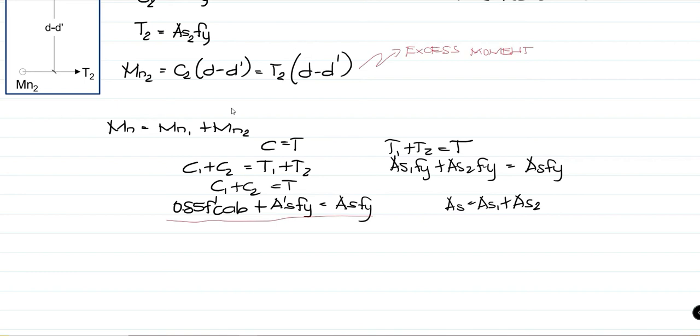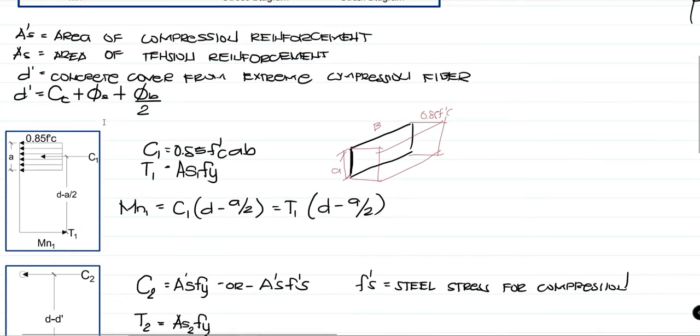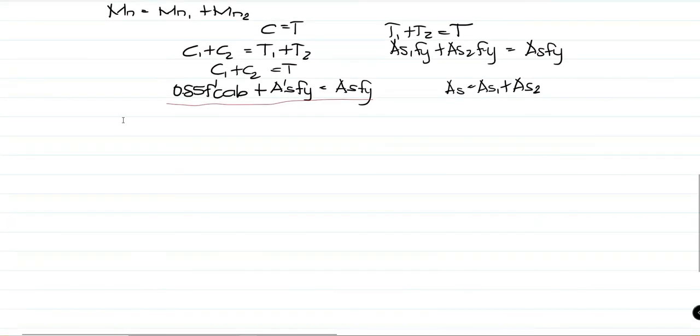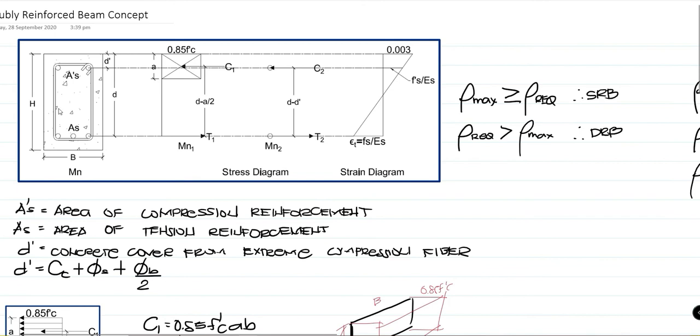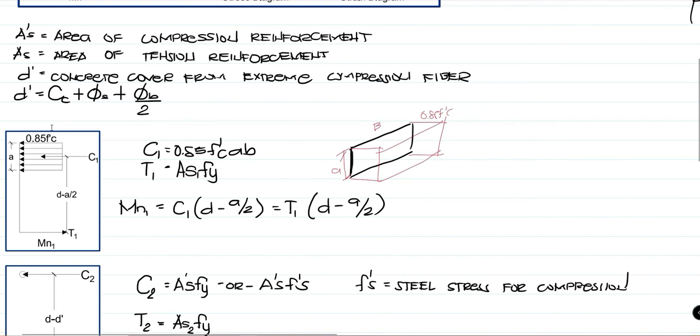Now, all of these values are just based on the assumptions coming from the diagram. But the code, NSCP 2015, says we need to deduct the strength that was lost in the hole created by our compression reinforcement. As you remembered from our previous topic, on the cracked and uncracked concrete, we always subtract area for this, right? When our concrete is punched through.